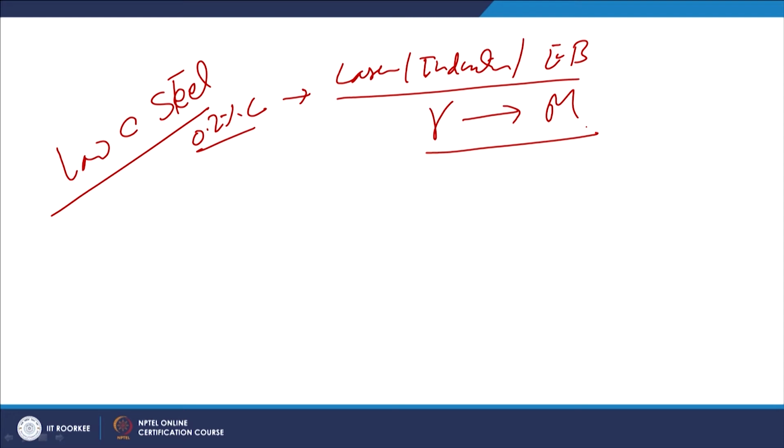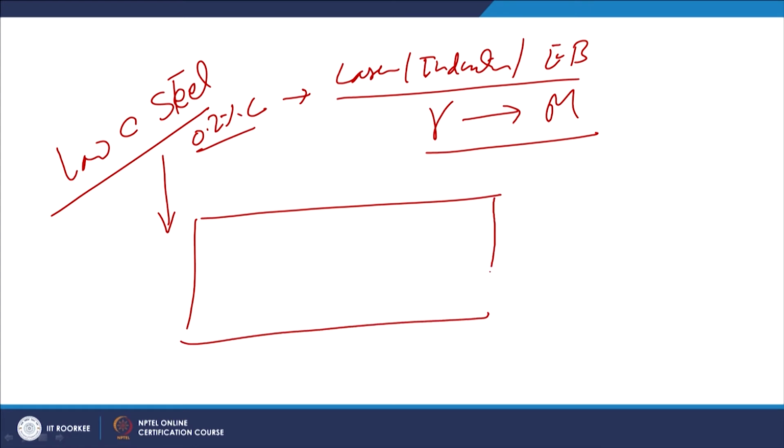Since the increase in hardness even due to this kind of transformation is limited, it is required that the carbon content of the surface layers in the steel is increased, and therefore, we use the method of carburizing.